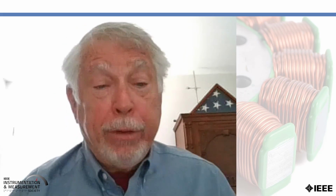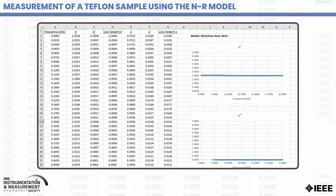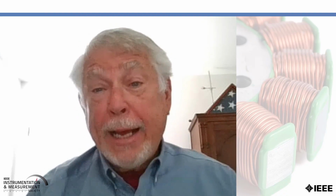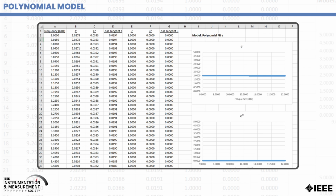When the measurement is triggered, the measurement is made, the calculation is performed using the selected model, and the results are displayed. One thing that should be noted in the table, we see that the magnetic properties are close, not exact, but close to 1 plus j0. So this gives us an idea that this must be a non-magnetic material, so maybe we would be better off using a different model. If we use a polynomial model, selecting that the model is non-magnetic, we get other results. And as we can see, they're pretty much what might be expected for a piece of Teflon.